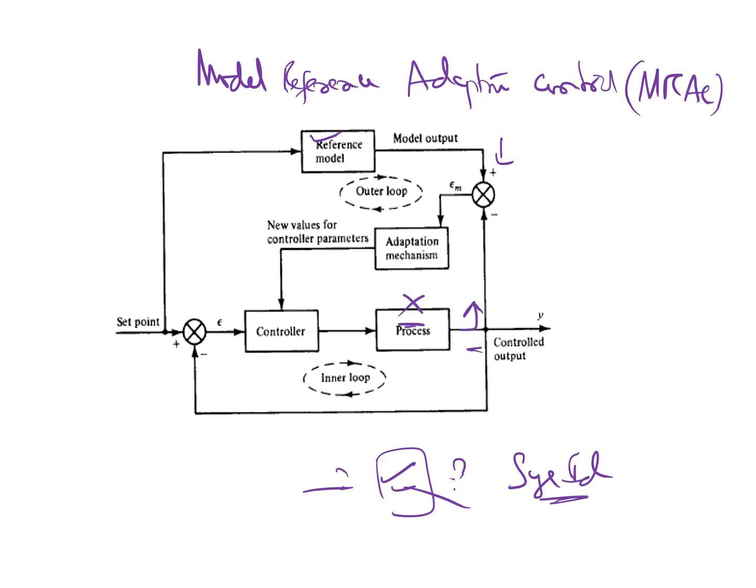Now we have to check whether the model you have framed is perfect or not. For that, give the same input to the model, and then this output. So now this is the model output and this is the actual output. You have to compare these and check the error. This error should always be minimum, then only the model is good. Because what is a self-adaptive controller?